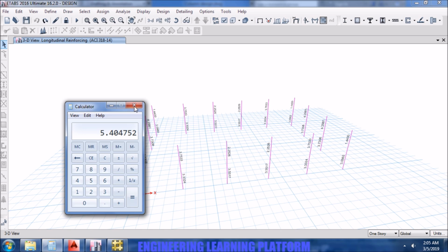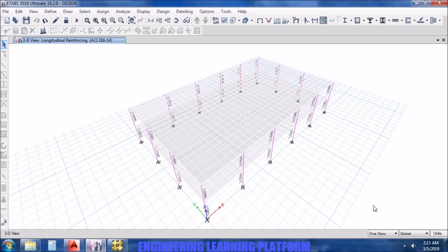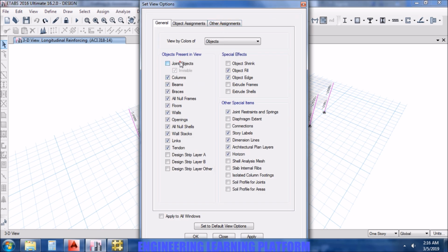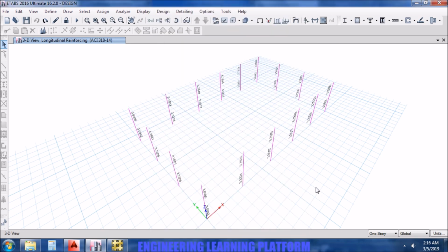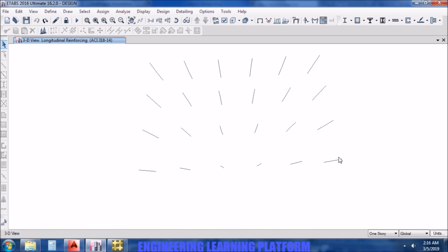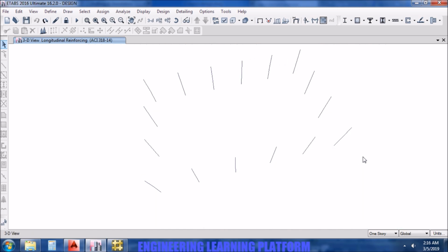So we are getting 5.4 inch square of steel for the bottom section of the column. So I would have reanalyzed the structure, assigning the 12 by 12 inch cross section so that forces are distributed according to their inertias and stiffness properties in spite of overwriting their properties.